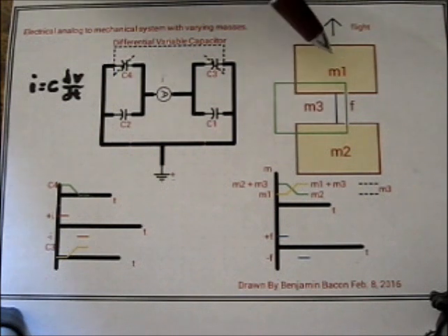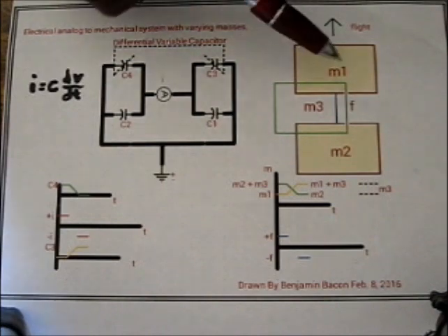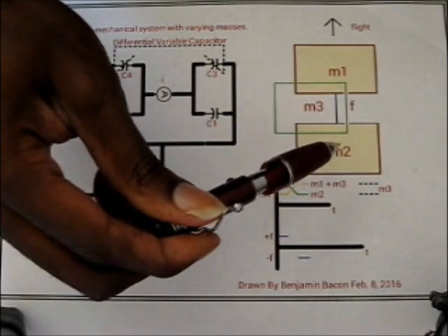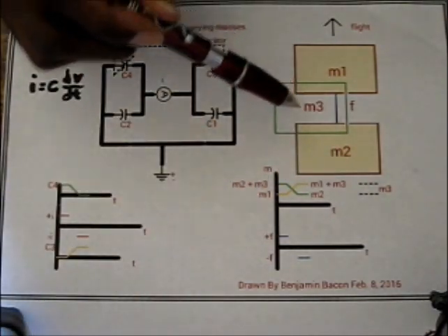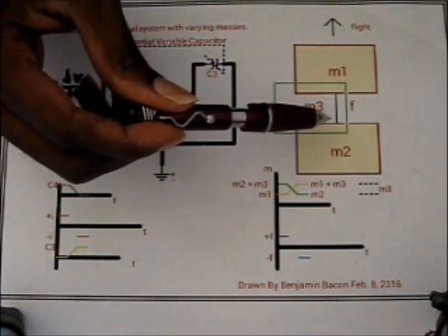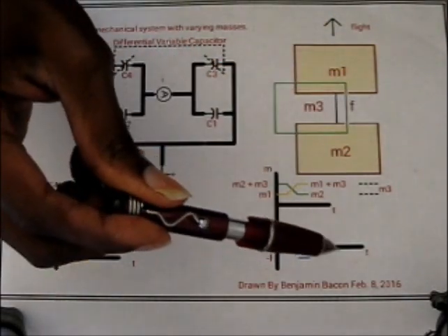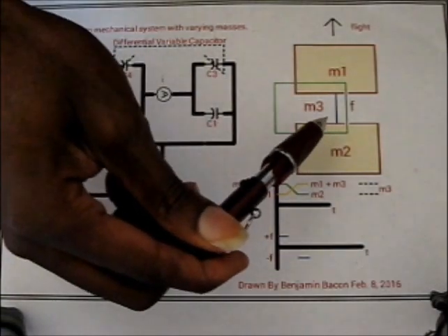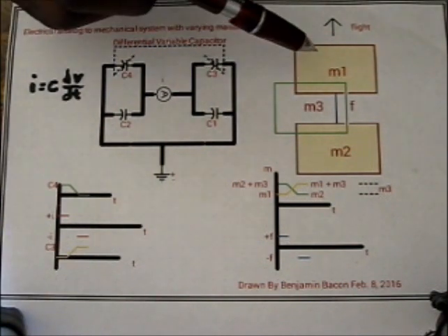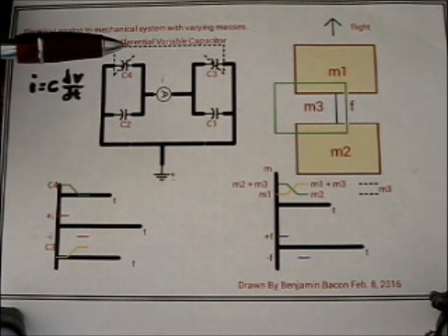However, when you're trying to build your simulator, you will find that if you don't model it correctly, you will get results such as it will fly this direction, and then after several cycles, it will start to go backwards and come back to where it began. Sometimes, if your model is not correct, the two masses begin to stray away from each other, and this gap between them becomes larger and larger, diverges, or sometimes they converge, and you have collisions and all kinds of events going on that you do not want to happen in the design. So that is why it's important to be able to get a very good model.